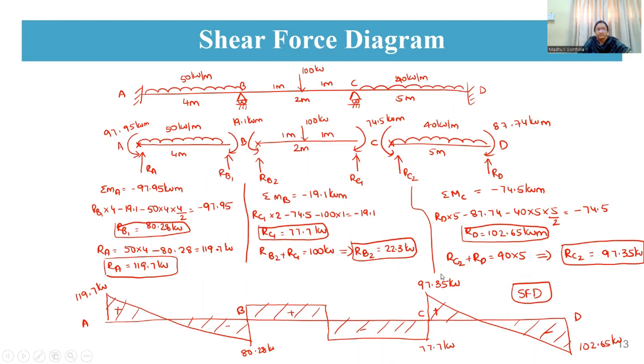I hope it is clear. Just simply as a simply supported shear force diagram you are going to draw, but you are going to calculate reactions with the help of the end moments also.